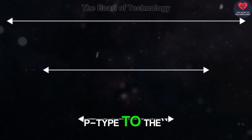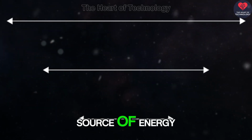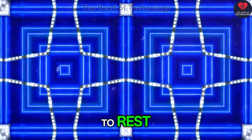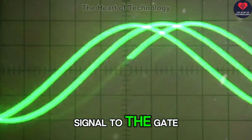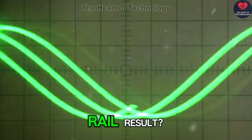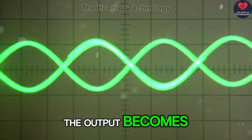Now, let's assemble our inverter circuit using our N-type and P-type workers. We connect the P-type to the power rail, the source of energy, and the N-type to the ground rail, where energy goes to rest. When you send a 0 signal to the gate, the P-type transistor turns on and connects the output to the power rail. Result? The output becomes a 1.